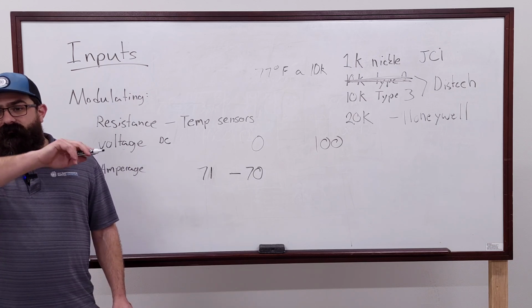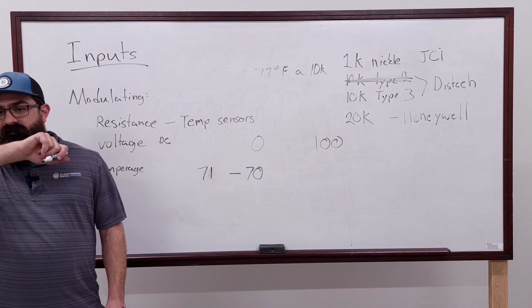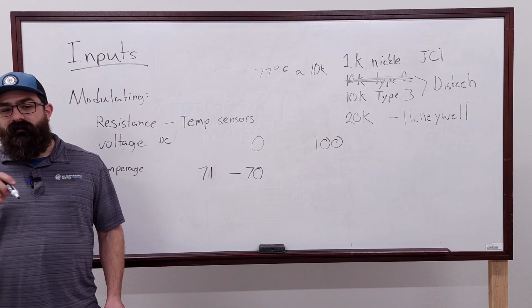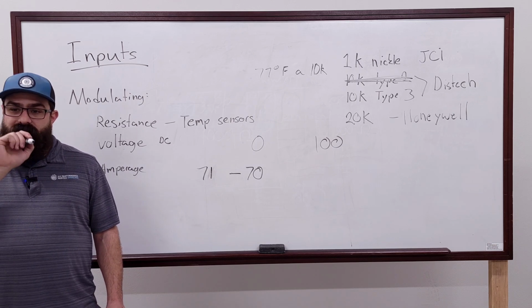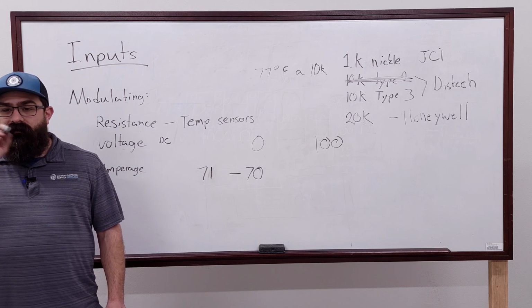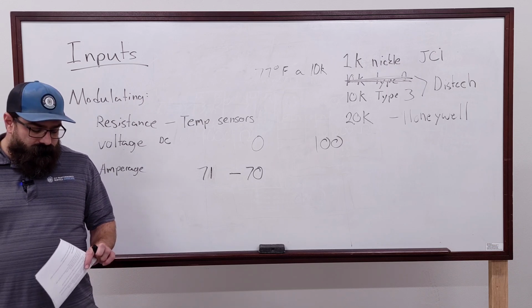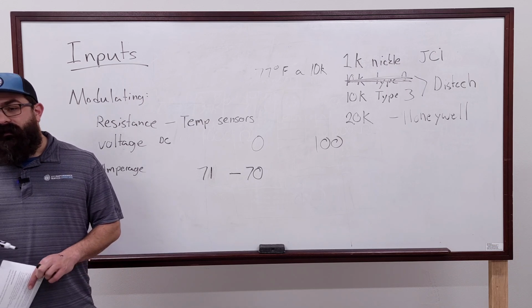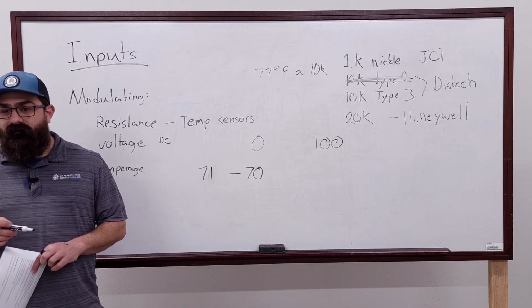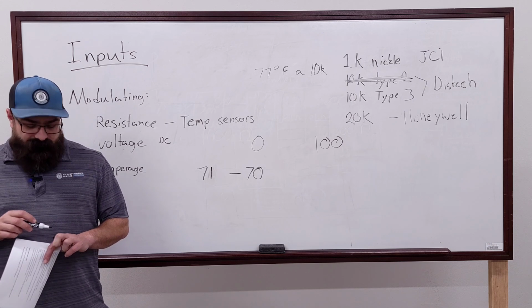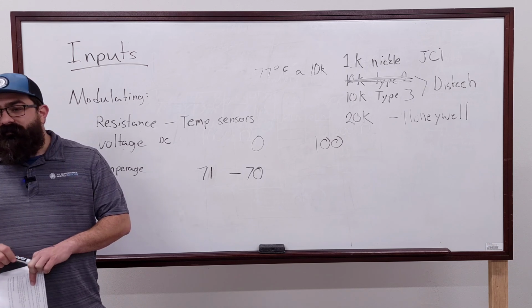So it may be reading 12,000 ohms technically at the sensor, but the logic block that's dropped in there pre-calculates it, and I never see the actual ohm reading. So I can configure them that way, but then I'm building the whole block myself, and it takes a whole lot more time. So we use the GUIs for a reason.